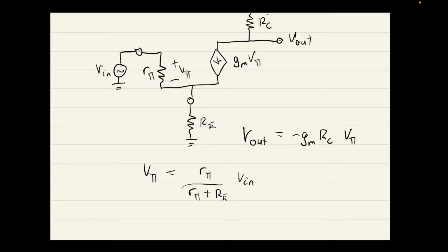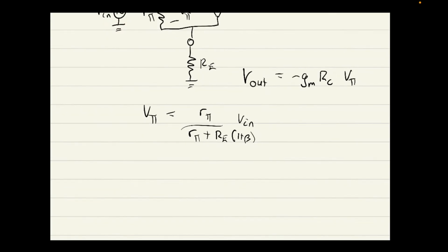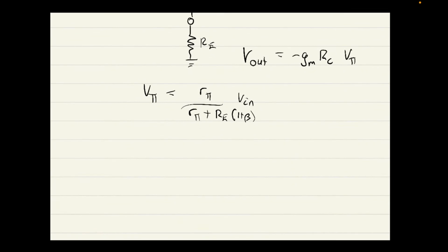Okay, so we end up getting this, but since we're going to take the resistor over from the emitter to the base side, we're going to add a 1 plus beta over here. Okay, sweet. Now, after some substitution, I'm not going to include the exact working out, but we get V in over there.